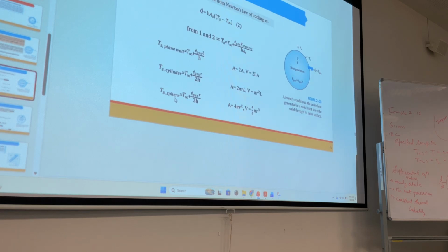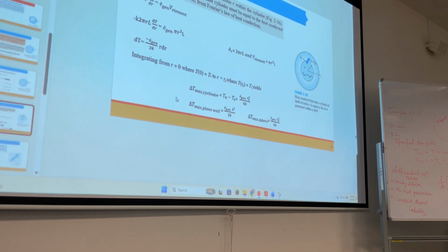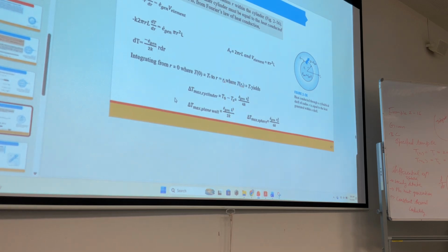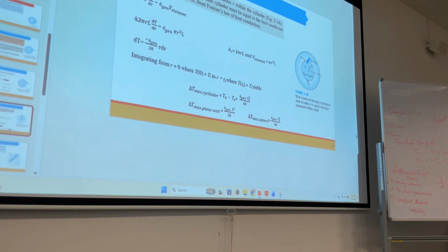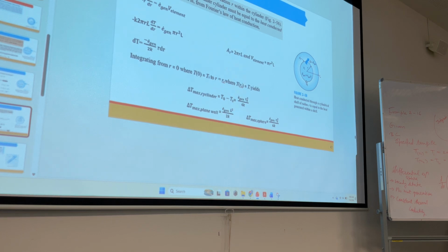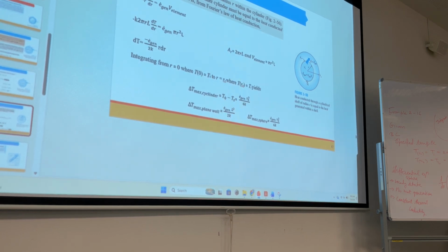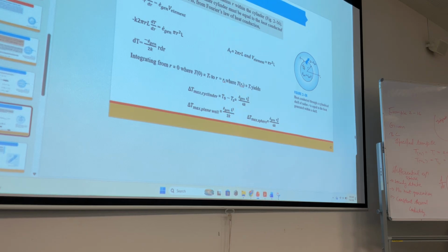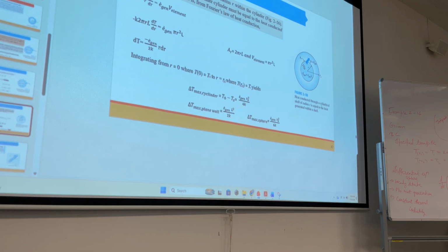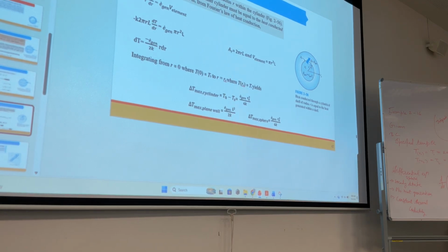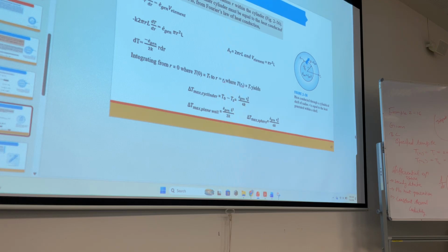Okay, so this is for one shape, right? If you have two spheres, two concentric spheres, in the small sphere the heat is generated and now the heat is lost to the outside sphere, not by convection but conduction, right? Because the outside sphere is also solid. So the heat transfer by this small sphere, the heat is generated first, right? There is a heat generation in the small sphere, and from the small sphere the heat is transferring to the bigger sphere by conduction only.